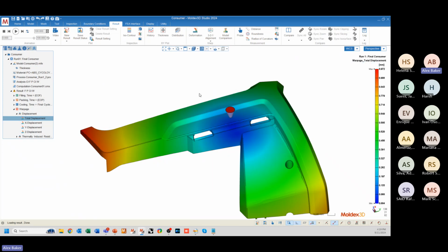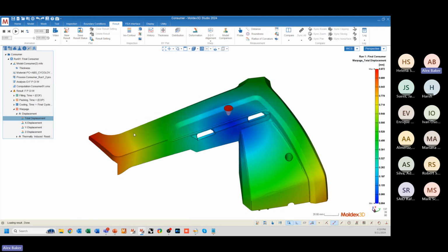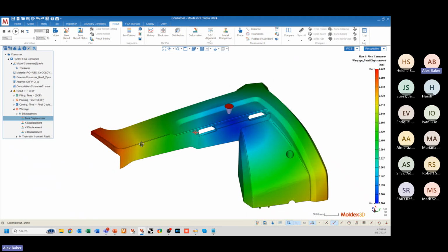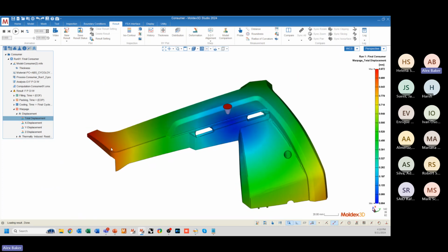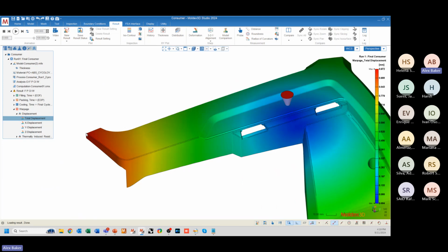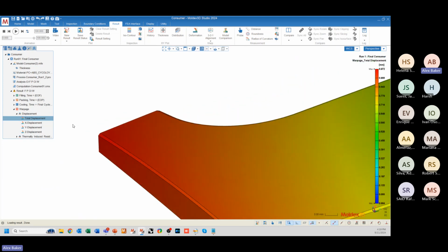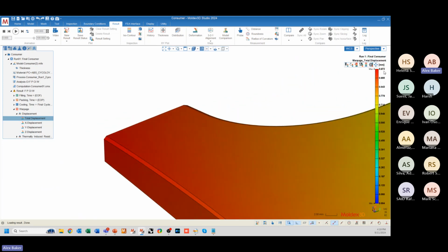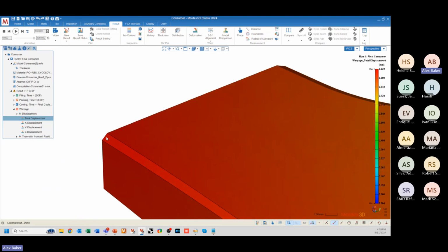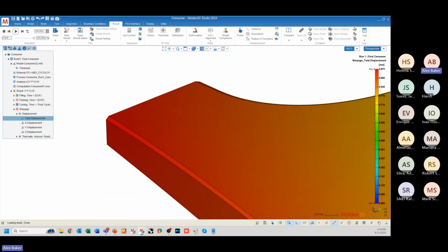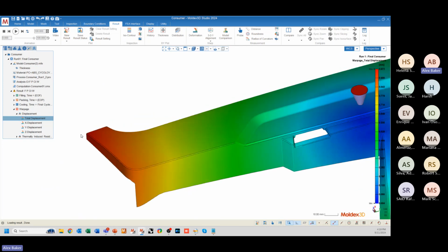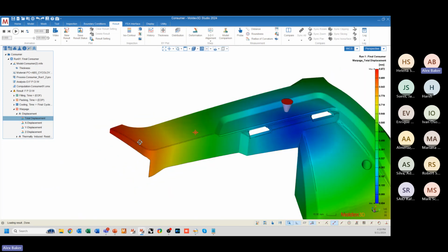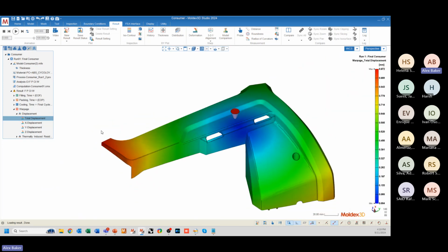And because of that, this total displacement does not ever give you a direction as far as how this material is displacing or how these nodes are moving from their original location. This is 0.972 millimeters of movement, but is that movement outwards? Is that movement downwards? Is that movement inwards towards the center of the part? Am I shrinking? Am I warping? This doesn't really tell me what direction these nodes are actually moving.